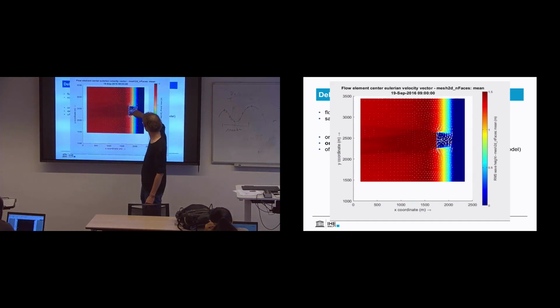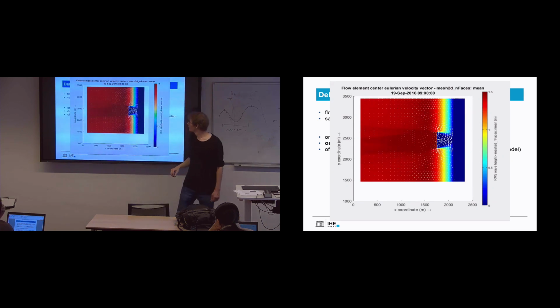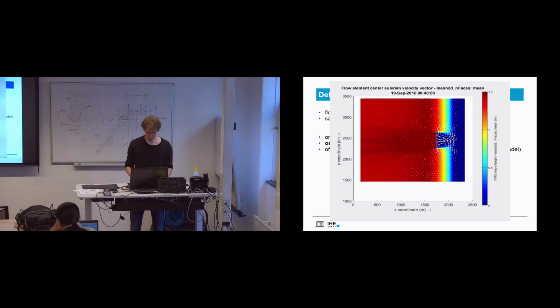There's a little breakwater here, and because you have differences in wave heights on either side of the breakwater and behind the breakwater, you have a flow that's actually going this direction and this direction, but because of continuity it can only go offshore, where it meets the breakwater, and then it has to go sideways, so you get these circulation cells as a result. Yeah? That's a little bit what happens. So, really cool.